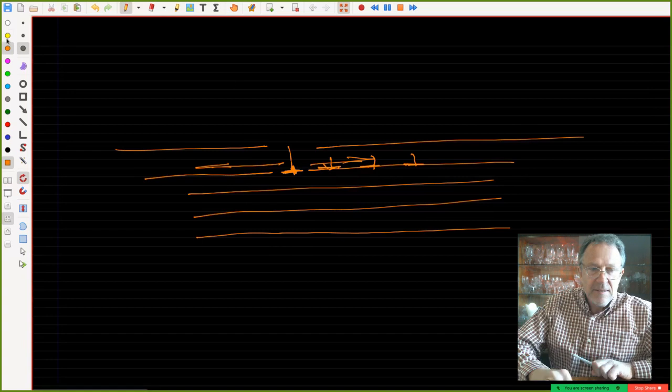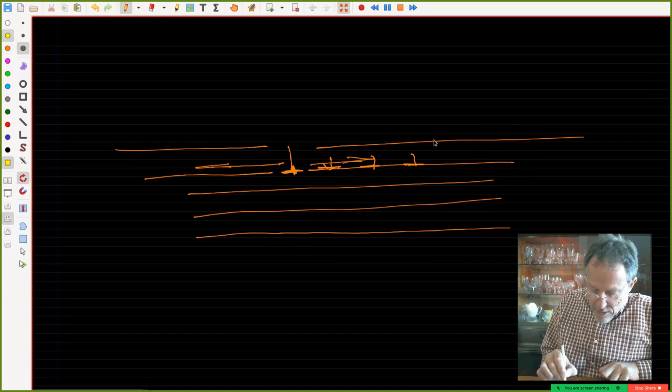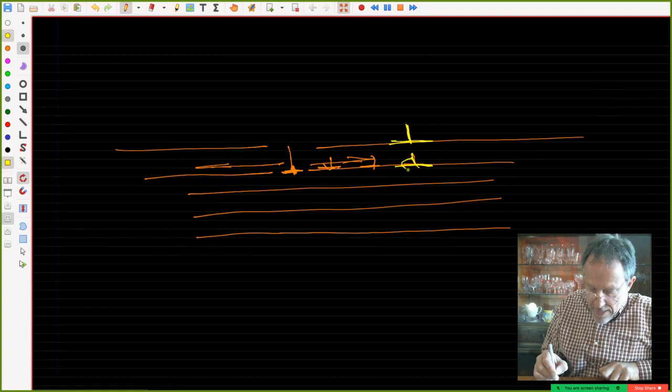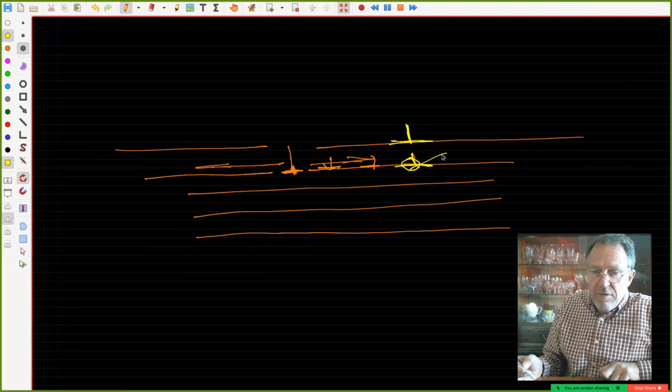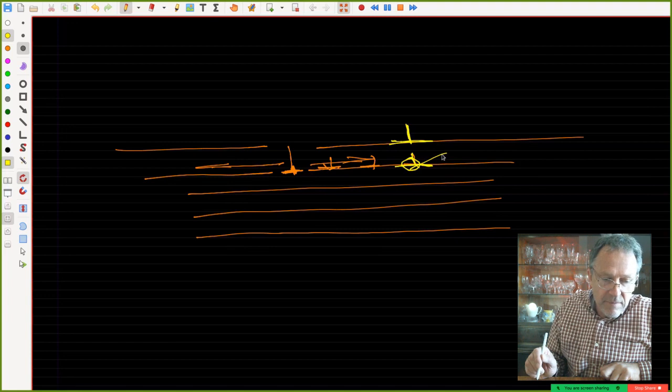Now the question is, how do I get it onto another slip plane? Let's say it is here, and I want to get it one plane up. Then I have to remove one atom here, and actually because this is a whole line, I have to remove a whole line of atoms perpendicular to the drawing plane, in the third dimension. That's called climb. And for that we need diffusion.